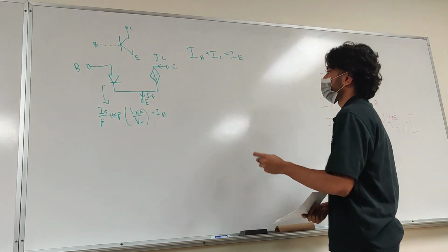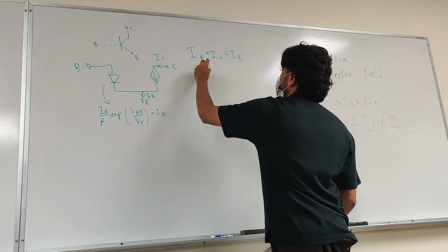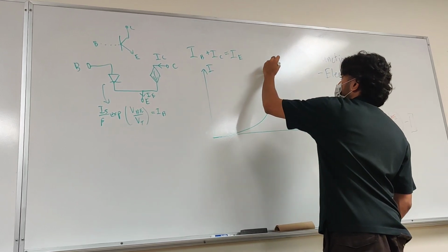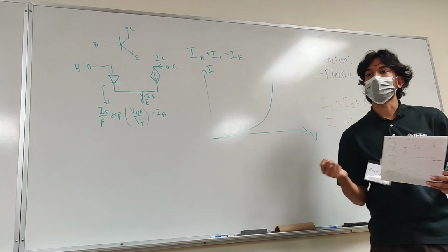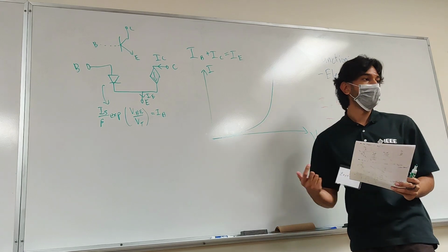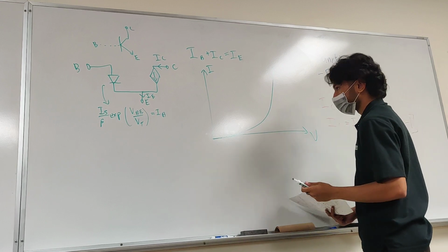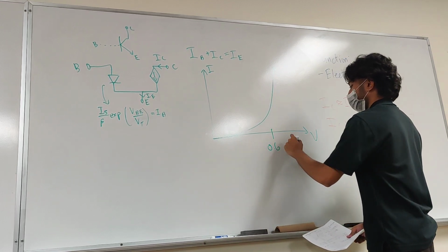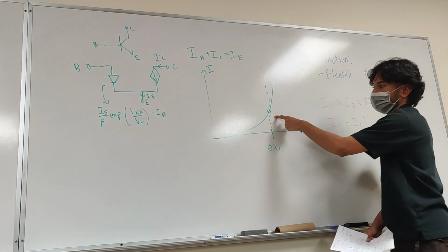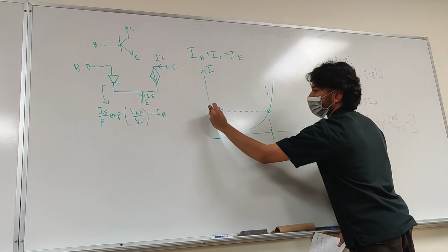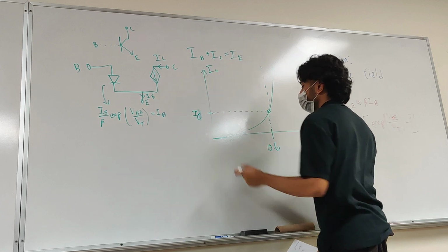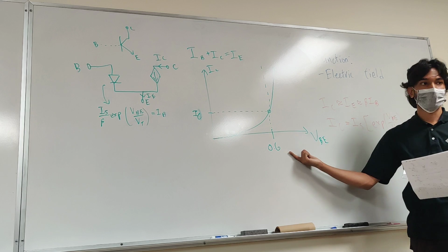This is where we now want to explore, going back to our PN junction, the idea of a small signal model. Okay, who here has seen a small signal model before, or heard of transconductance? Okay, good. So I'm guessing a lot of 115A people. Okay, so what happens here is, let's say we are at 0.6 for our VBE, so we're somewhere here. We have a certain current as a result, IC. So we have a certain current resulting from a certain VBE.